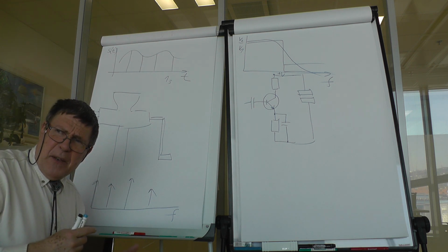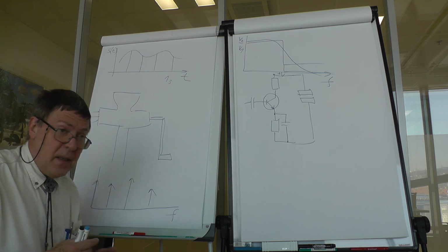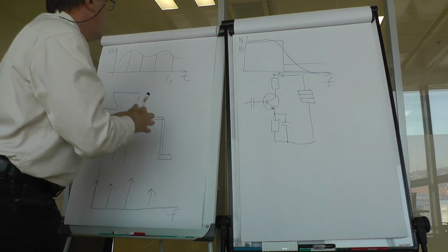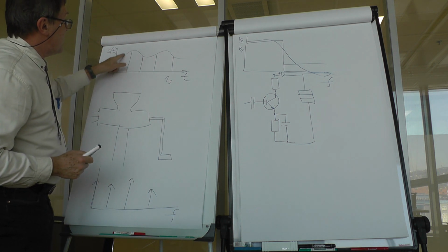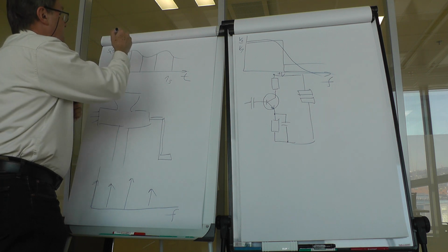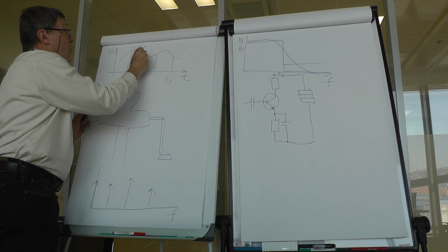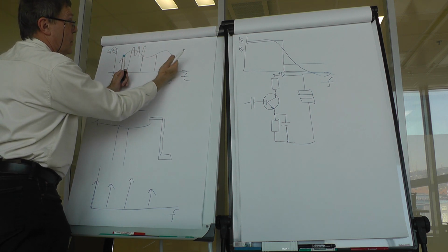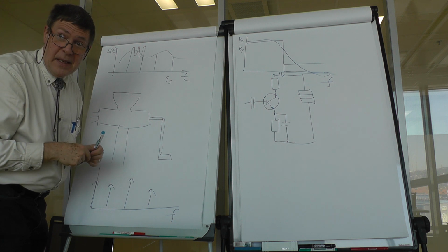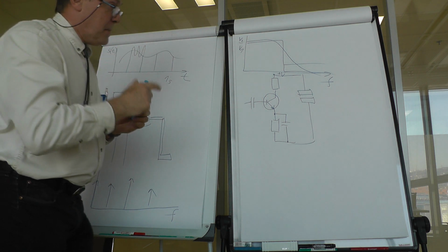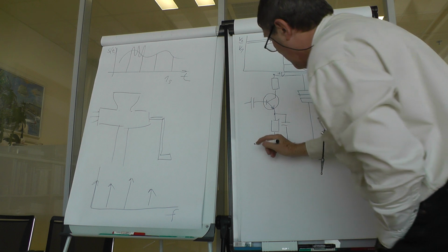So what happens if we undersample the signal? Well, in fact, if this signal would be, for example, of this kind, with this sampling you would not reveal it. But something strange happens, and that's called mirroring.